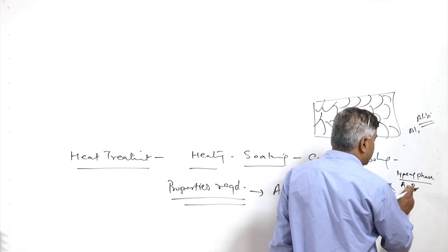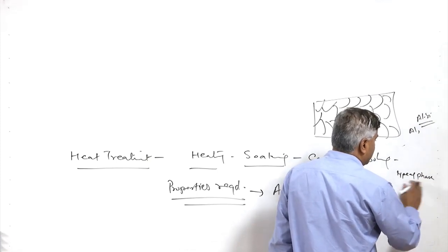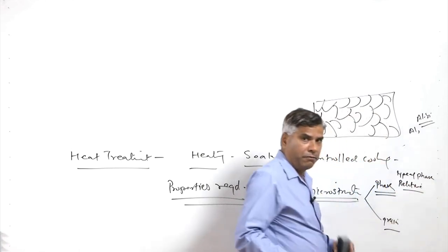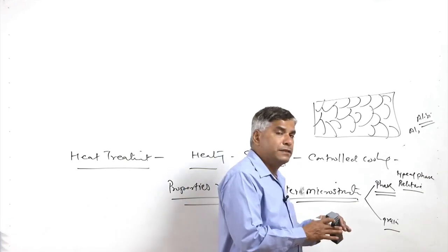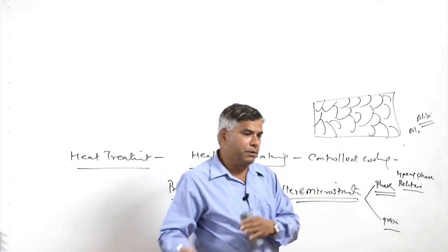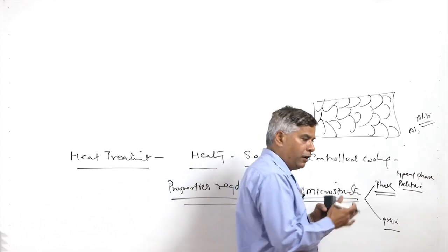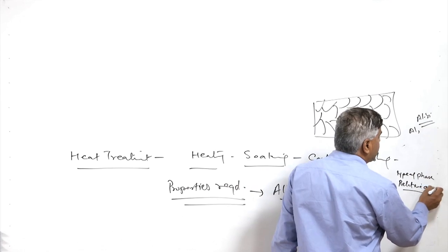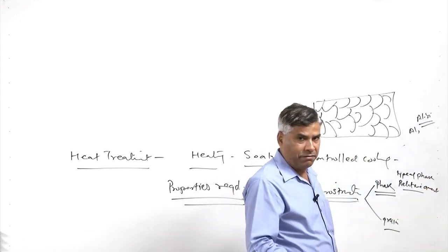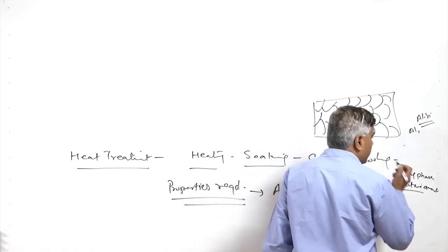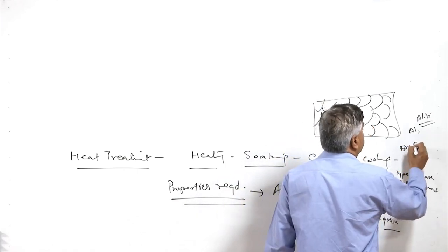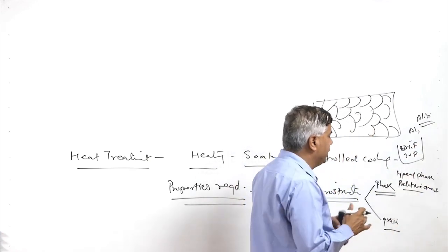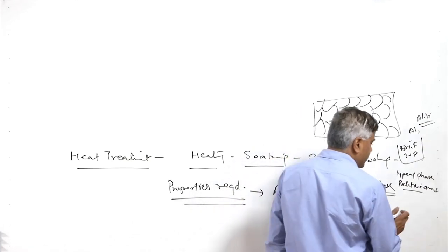So, what are the different types of phases present in the metal and their relative amounts matter, since each phase offers a different set of properties. If the soft phase is present in greater proportion compared to the hard phases, in general the metal will be of lower strength and lower hardness. So, the relative amount of the different phases could be, like, soft phases 10% and hard phases 90%. A low carbon steel may have 80% ferrite and 20% pearlite. So, it is about the proportion, or relative amount, of the different phases which are present.